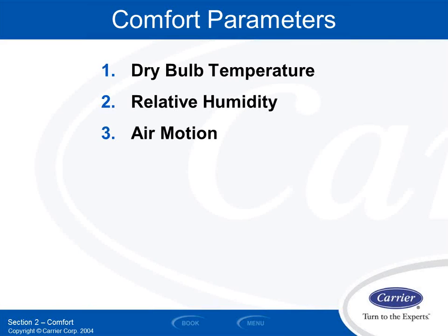The next one is air motion. Not only do you need to have appropriate temperatures and humidities in the occupied space, but you may have to have more or less airflow to make people comfortable, depending on whether they're cold or hot, right? When I was a kid, I didn't have air conditioning growing up, but I'd come in from outside all hot and sweaty. The first place I would go stand was in front of a box fan. The temperature on the inlet side of the fan and the outlet side of the fan was not any cooler. In fact, it was probably slightly warmer because there was some waste heat from the motor. But to me, it felt way cooler than if I was just standing there with no airflow, right?